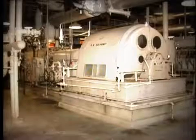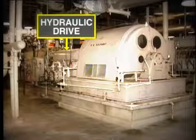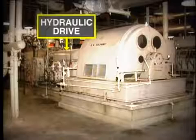Of course, the same result can be achieved by applying a variable speed hydraulic drive between an electric motor and the pump. The ability to control the quantity of water being pumped into the boiler is vital for safe boiler operation, and the control system must be able to respond rapidly to changes in water level in the boiler caused by variation in turbine load.